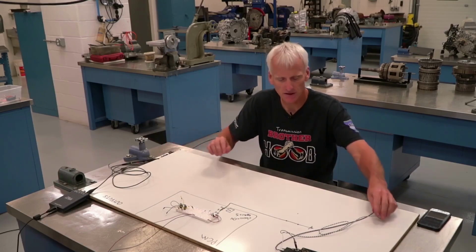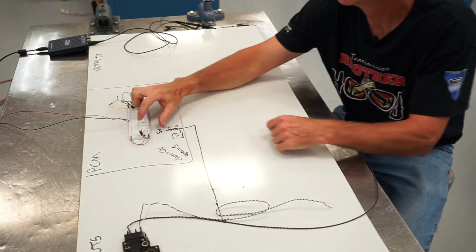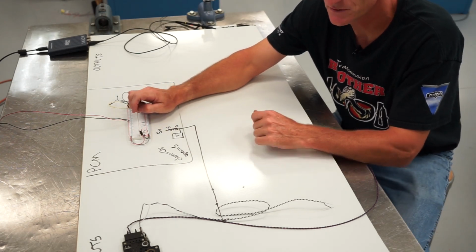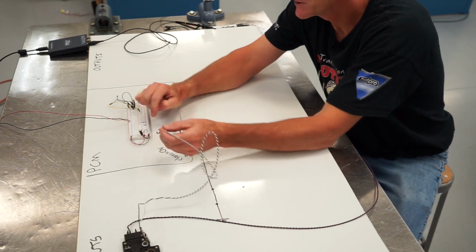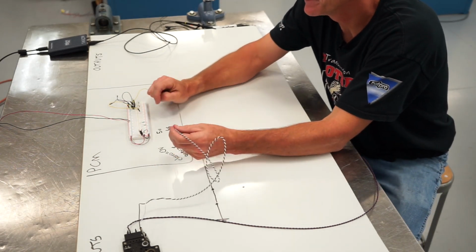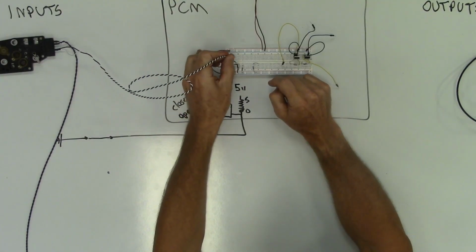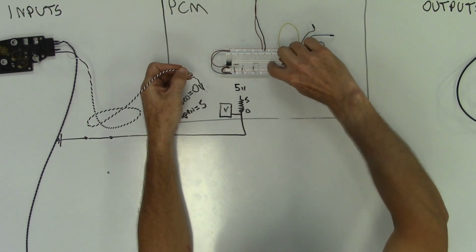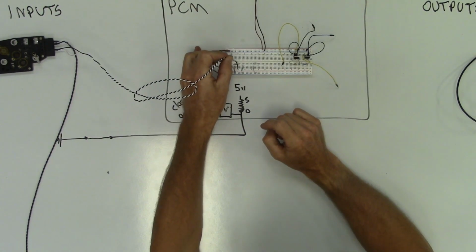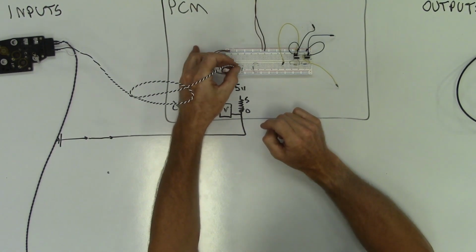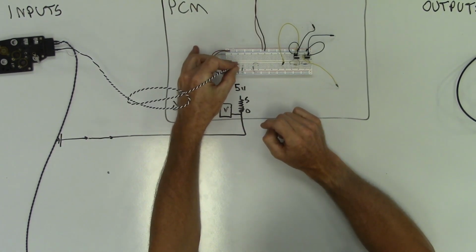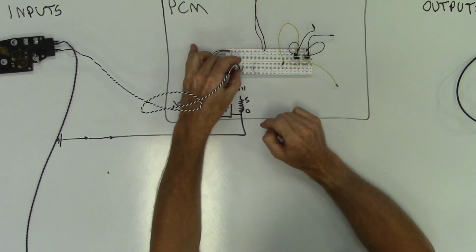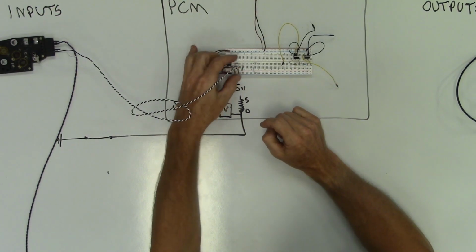So we can go ahead and wire this up, and we'll see if we can make it happen. Right here, there's a tiny little resistor. I don't remember, I think I put a 10,000 ohm resistor in there. But that's going to mimic this resistor right there. And on these breadboards, they connect these rows together. And so if I go between ground and that row, so what I've done, get in there, okay.